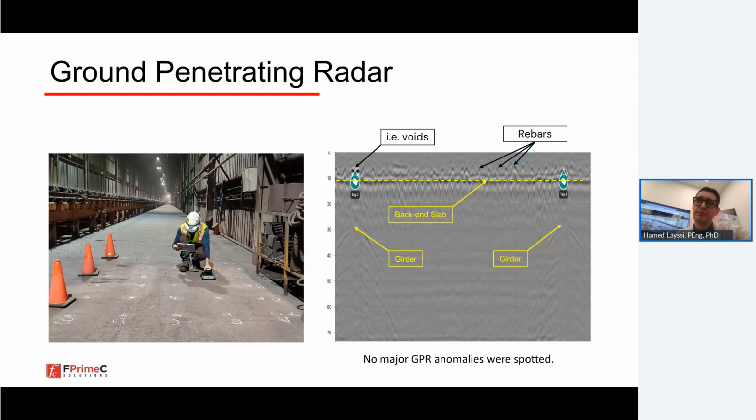Now, from the bottom side, it had a very small cover thickness, and our understanding was that at the areas where this cover might have been reduced from the minimum specified cover thickness, we are seeing those signs of corrosion.